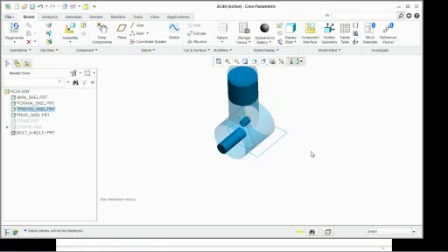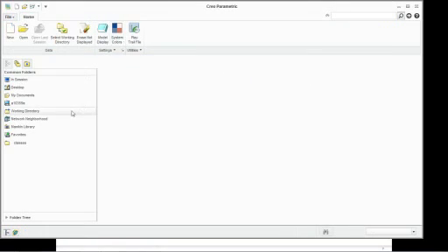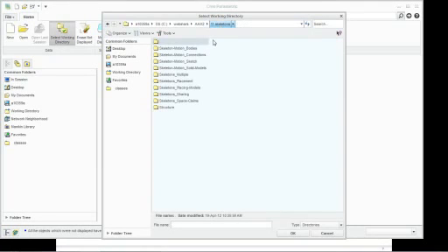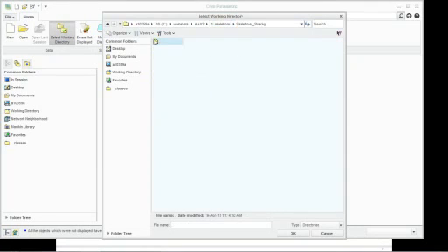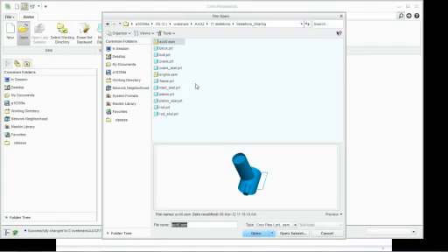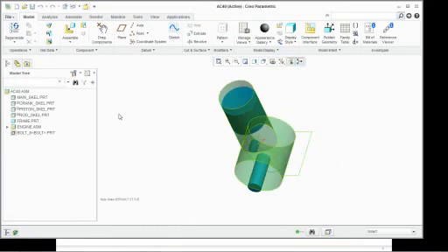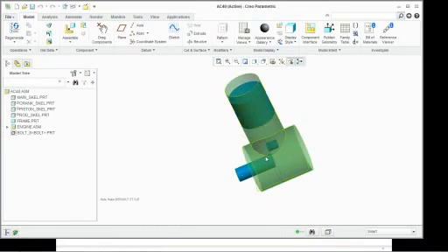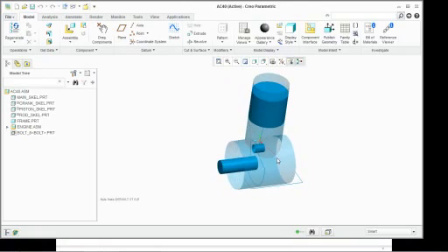So now you're saying, well, big deal. Skeletons don't really, I can't give a skeleton to a customer. I need to create some solid geometry. Well, how am I going to do that? Well, let's open up the next section here. We're going to close out of here. Erase not displayed. We're going to set the working directory again. This time we're going to pick sharing skeletons, which is going to allow us to go in and take that geometry that we've created and make sure that we can create solid geometry from that.